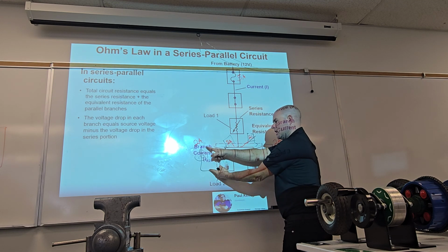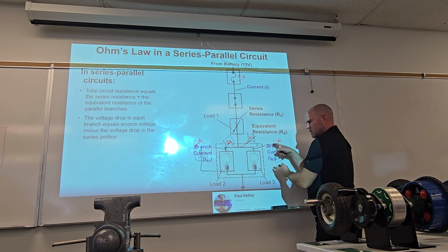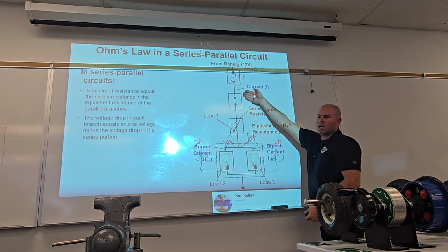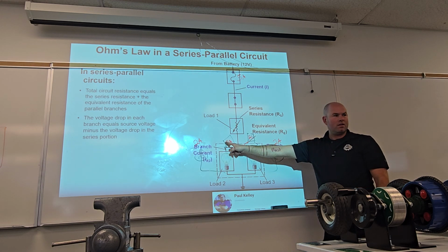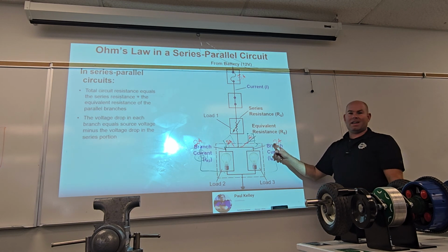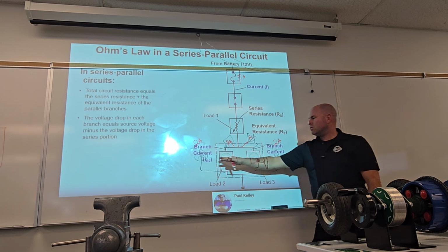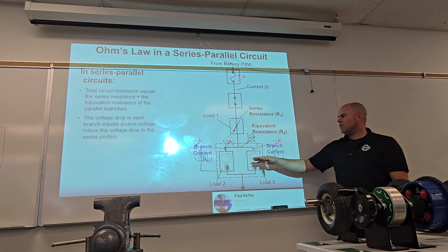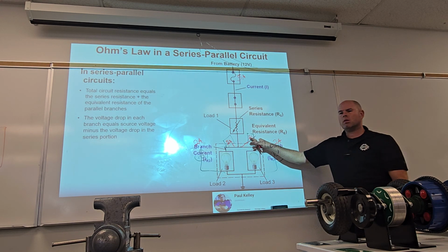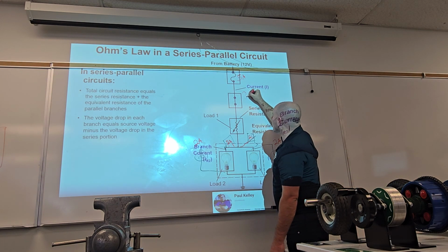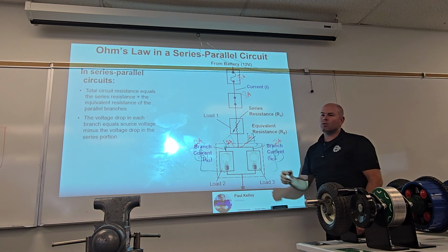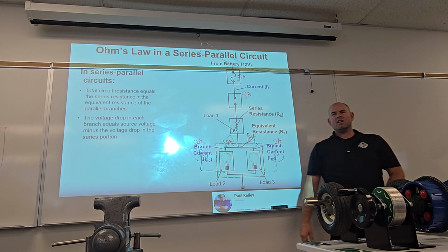It didn't increase it right here. It didn't increase it right here. These stayed the same. But how many amps do you have here now? 2, 4, 6, 8. Make sense? Now you just did 4 lanes. So if you have 2 cars and 2 cars and 2 cars and 2 cars, that means back here you had 8 cars. So if you have 8 amps, what's up with that fuse? It's blown. So what do you do?